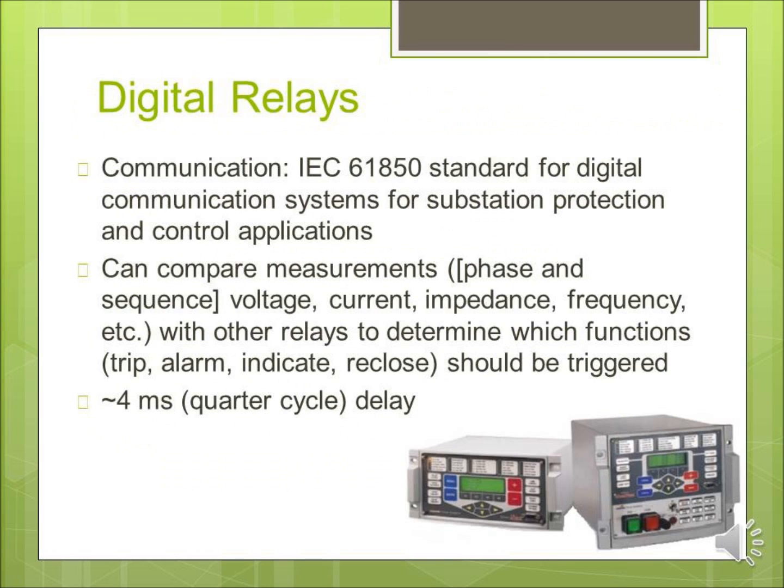The use of digital relays is important for the development of microgrids because they can communicate. Digital relays communicate using the IEC 61850 standard to compare measurements with other relays rather than trip at certain settings, like traditional electromechanical relays.